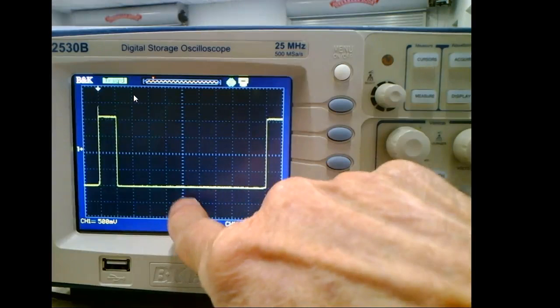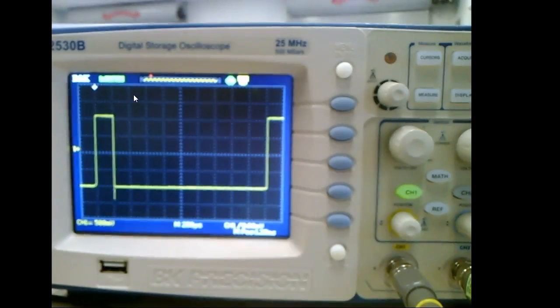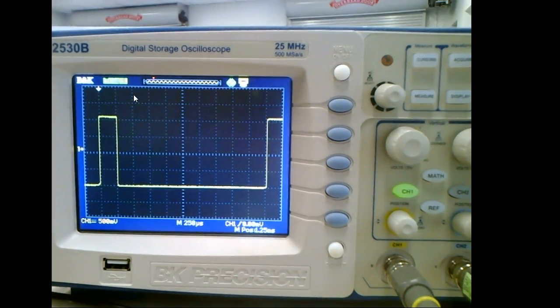So at 10%, 1, 2, 3, 4 volts. At 10%, my motor would see this at 1 volt. And it would run at whatever speed 1 volt would tell it to run at, right? Here it would run at what? It would see it as what? 2 volts. Here it would see it as what? 3 volts, right? So let's get one of our meters.